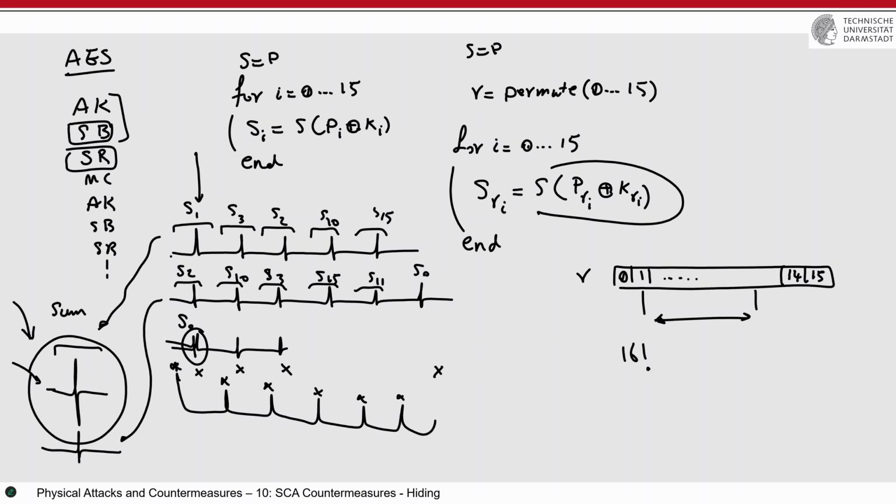You may say that, okay, this is the AddRoundKey. If you want to swap between ShiftRows and SubBytes, then you should either first realize the AddRoundKey and then decide whether you want to swap ShiftRows and SubBytes, or you apply the ShiftRows on the key values and plaintext as well, before doing the S-box. All of these are just byte-wise operations, the AddRoundKey, SubBytes, and ShiftRows. And as long as you do not mix the bytes, similar to MixColumns, you can swap them easily, randomly swapped.